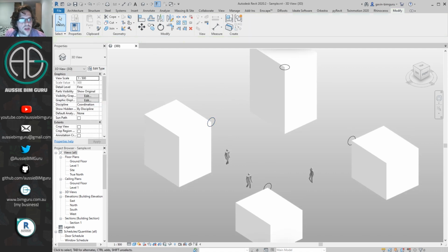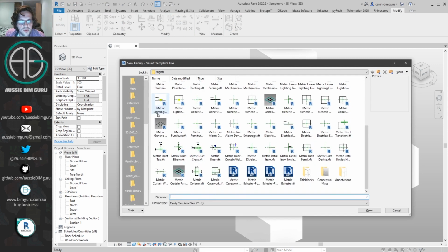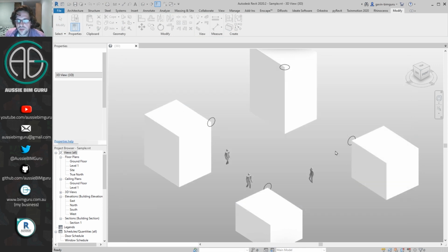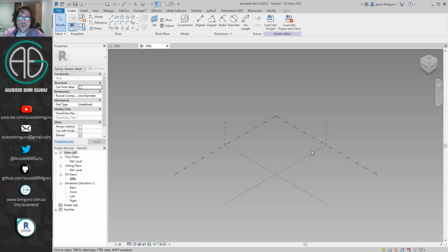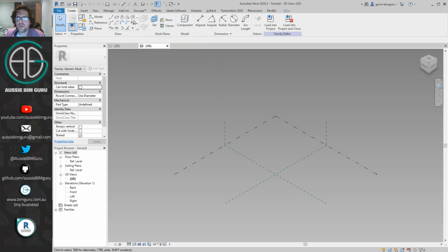Now to build one of these, it's quite easy. All you have to do is go New Family, and again, we're going to make an adaptive component. And these are really just like anchor points to guide Rhino Inside for where to hang the shade from. So in this case, you could work with more than one placement point to hang this component from, as long as your adaptive component is built, I guess, to build up the framework of this element.